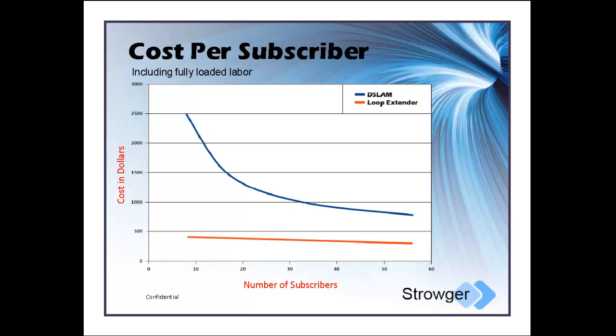The big problem you face when trying to deliver DSL to everybody in your serving area is that your last few subscribers in the serving area are fairly sparse. So trying to deliver DSL to these last few subscribers with a traditional DSLAM method can get quite expensive. The big problem with the traditional DSLAM method is that the cost for your fiber cable and the cost for your power is a large part of the total installation of the project. The actual cost of the DSLAM is almost inconsequential.